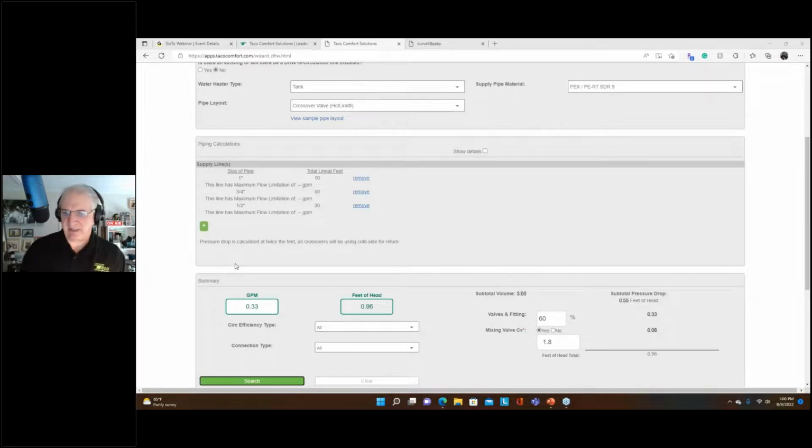Additionally, in a vacation, it has an automatic vacation mode. If it does not sense a hot water event, meaning an increase in temperature, sustained use, and then a drop, if it doesn't sense an event for, I think it's 36 hours, might be 72 hours, it basically says, you know what? Nobody home. I'm going into vacation mode. I'm going to run for a couple minutes maybe once a week until somebody gets back. And then once somebody gets back and turns on a hot water fixture, we start the learning mode all over again. So those are different ways to enable the circulator in a standard domestic hot water application.